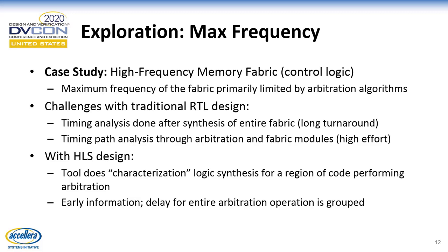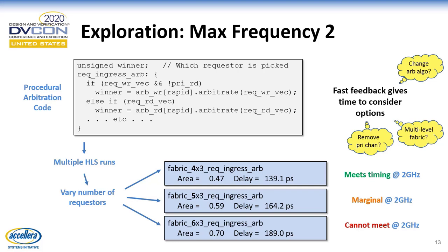Okay, good luck. That's going to be a whole new set of effort there. When you're using the HLS tool, what's nice is because it has the technology library, as it goes along, it will be characterizing the operations in your code or even regions of your code. You can have it characterized for timing and area. Let me show what this means a bit more.